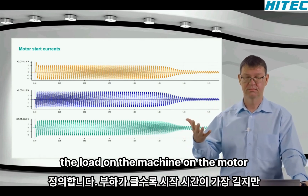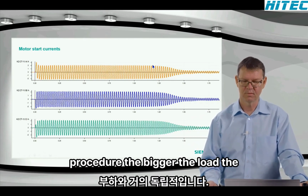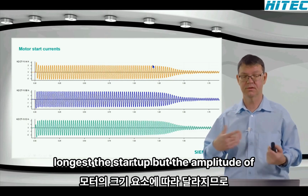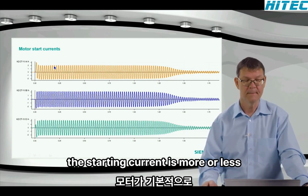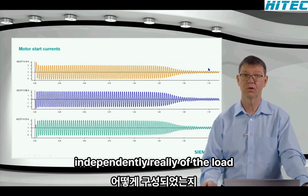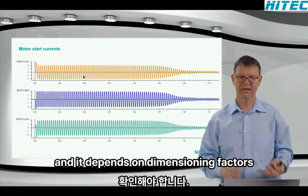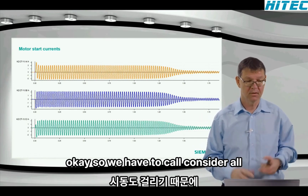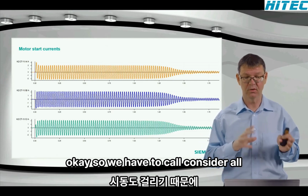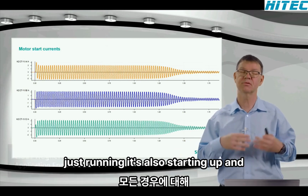The load on the motor defines how long the startup procedure is. The bigger the load, the longer the startup. But the amplitude of the starting current is more or less independent of the load. It depends on dimensioning factors of the motor, so how the motor was constructed basically. Okay, so we have to consider all these aspects because the motor is not just running, it's also starting up.